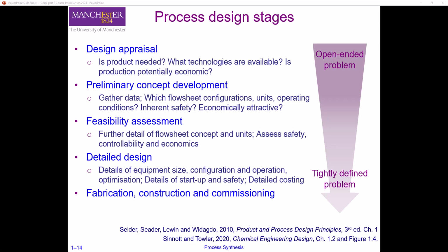The next step is the process design concept. This step looks at the proposed process in a little bit more detail and puts together a flow sheet. The flow sheet normally includes, for example, different processing steps and what unit operations to include, and also the associated operating conditions, or at least a rough estimate of these operating conditions. At this stage, you should have enough information to look at the safety of the plant and the implications of different steps.